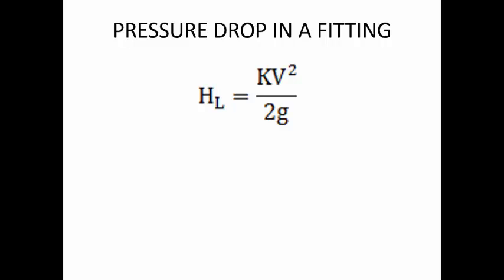So the two are equal, and theoretically we say that the pump can drive the actuator to get the required work. But you have not considered the losses in the piping arrangement. You have a lot of valves, large lengths of pipes, a lot of fittings, and a lot of measuring devices which change the area of flow. Because of all these things, you will have a significant amount of pressure loss.